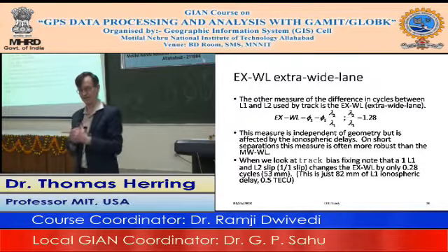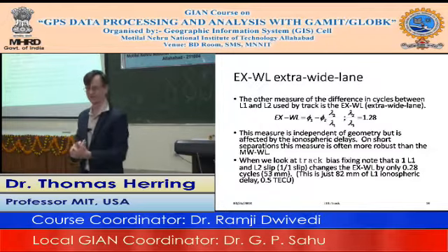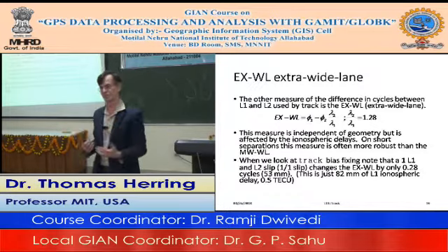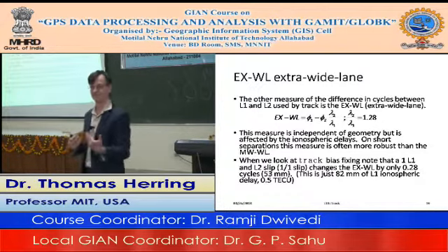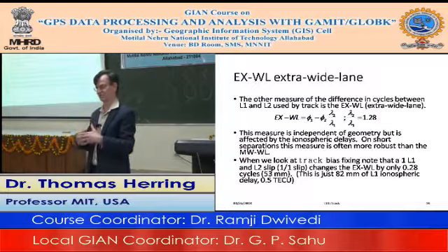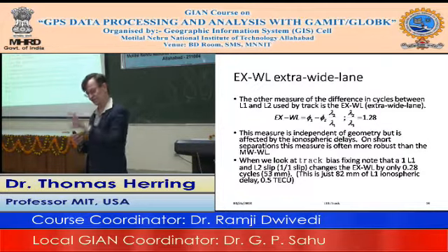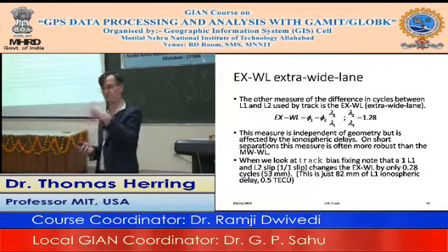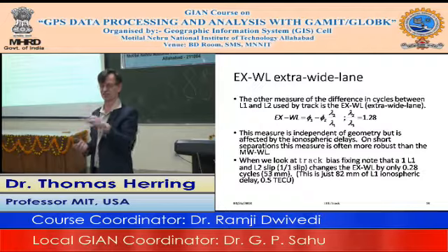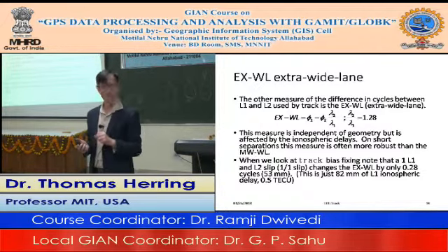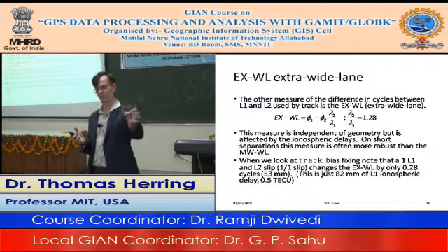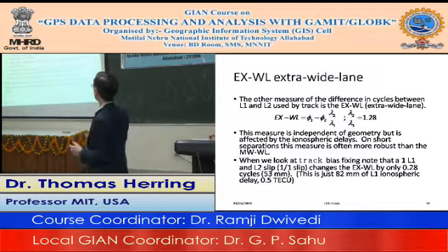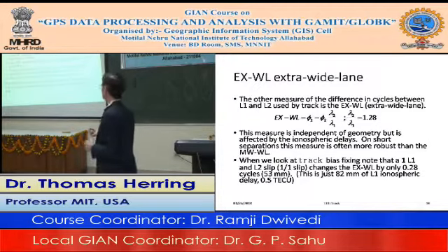Again, as you go to longer baselines, it gets harder. So what do you have to give to track? Track is like GLOBK: it runs on a command file. As I think about it, we don't actually give any templates for it, simply because the basic elements are always the same, but the names of things are very different all the way through. You might have noticed in the GLOBK templates, we didn't need to change very much, because all of the files we were referring to were standard files.